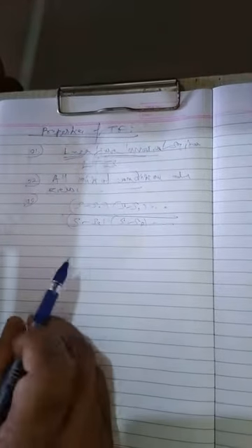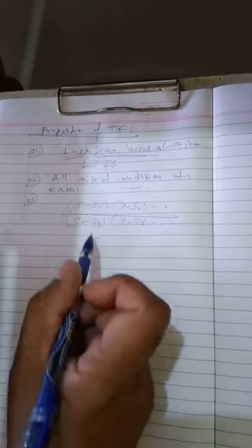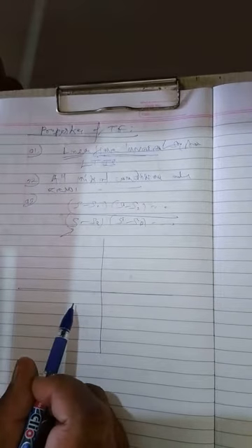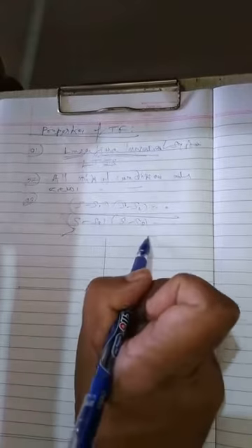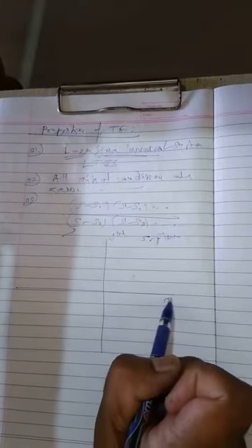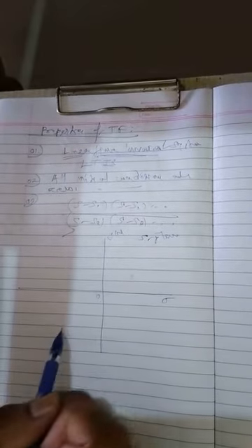s minus sa, s minus sb are, suppose, poles of the transfer function. Here s is nothing but a complex variable. So we represent these poles and zeros in the s plane. In the s plane, the j omega axis is the y axis and the x axis is called the real axis; the origin is 0.